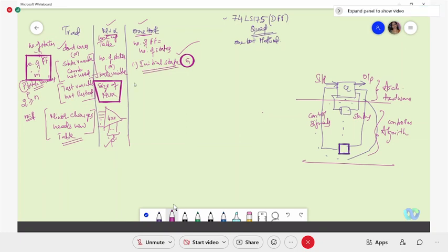It's not the wanted output. It can be a valid output, but not a wanted output. Valid in the sense, say you have 4 states. If you start by default at any of S2, S3, or S4 rather than S1, for the next clock, based on the present condition, it will derive what will be the next value. Because these are all linked up. In your one hot, once you start, the next state will be automatically generated based on the present state and the present input that is available to the design at that moment of the clock.